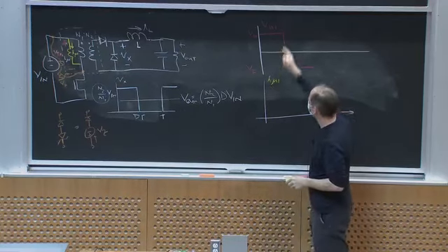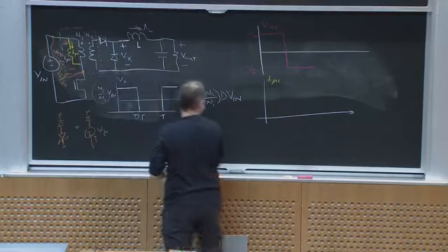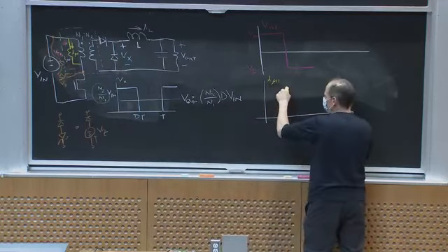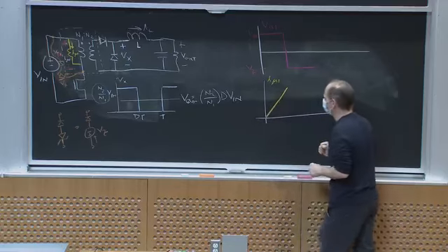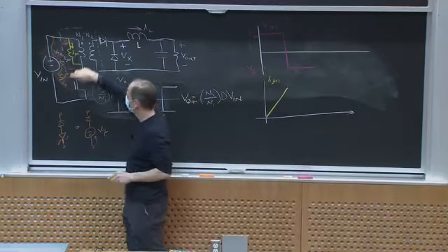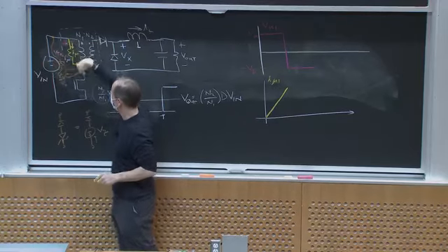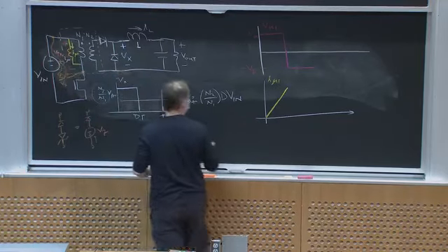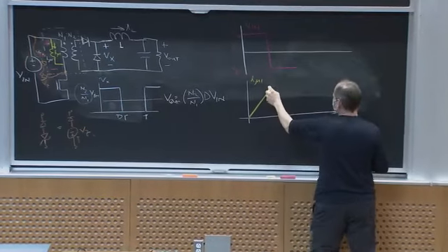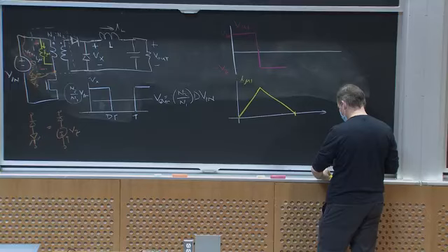Okay? When I turn on the switch, it's going to ramp up. Let's assume it ramps up from 0, like this. And then I turn off the switch. This current, the magnetizing current, cycles into this, and it ramps down because I have a negative voltage. And eventually what I would like is for this to hit 0 at some time.